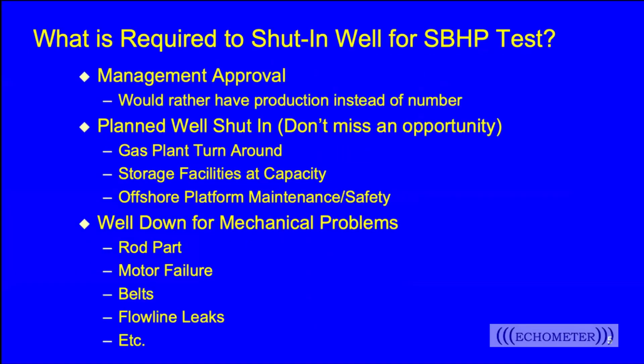So what do we need to do to get a static bottom hole pressure test? Well, typically we would need management approval in the normal producing time. But most managers would rather have the production and the money in the bank instead of the number for the static bottom hole pressure. So we should really take advantage of times when there's a planned shut-in, and we shouldn't miss this opportunity.